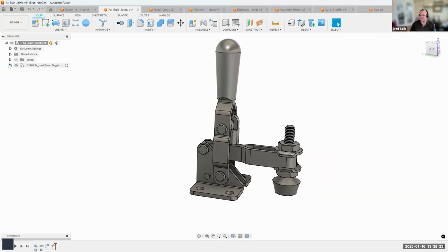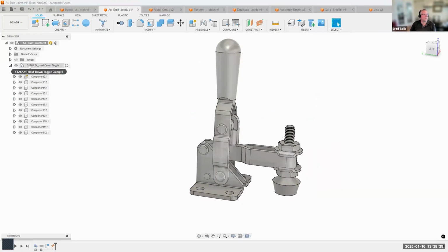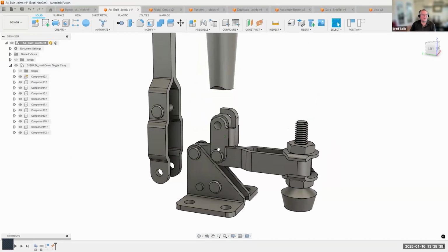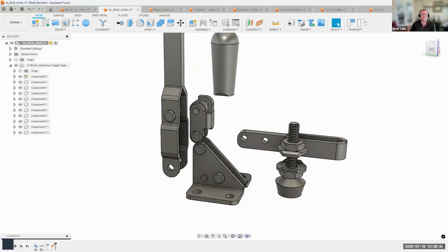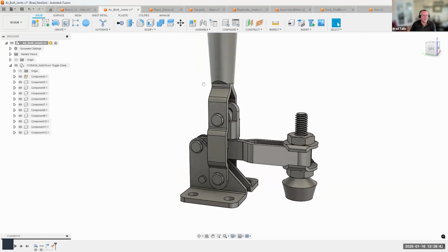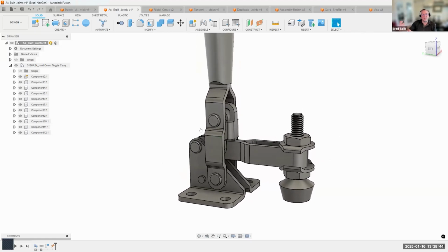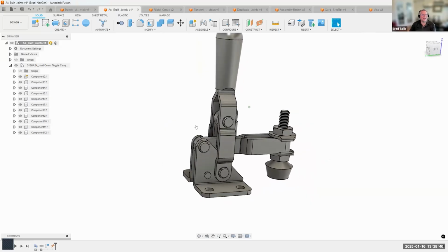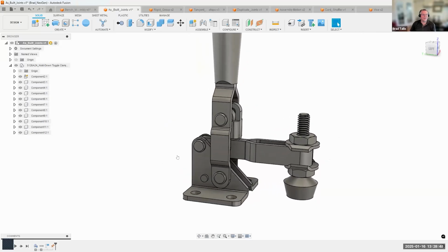And this will actually answer the question. I can't remember. Oh, I actually already converted them. They come in as bodies. I just right mouse clicked and said convert bodies into components. And you can see that they're now components, and they have no assembly structure whatsoever. However, it's already assembled, right? They're already in the correct location.